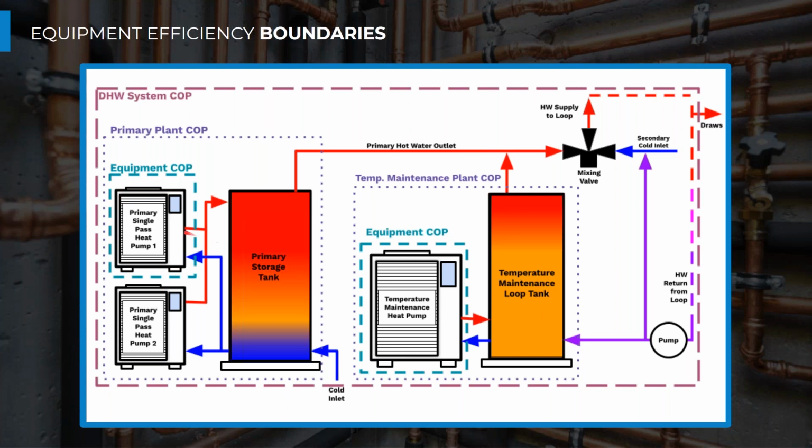However, just for cost savings, instead of putting a flow meter on that heat pump and one on that heat pump, we just put one here to get a totalized flow of both the heat pumps there.